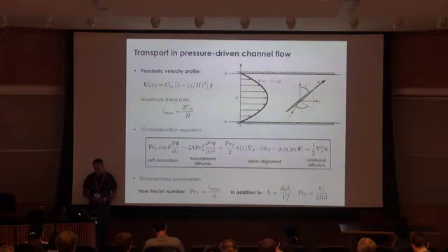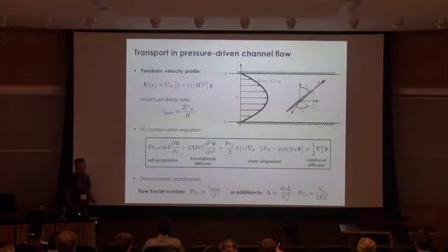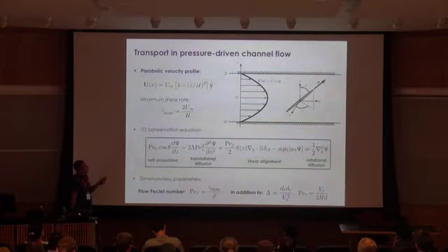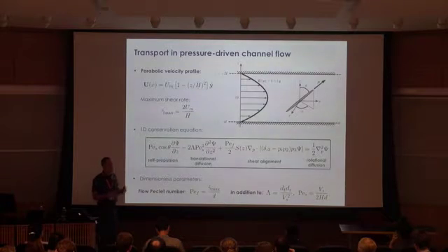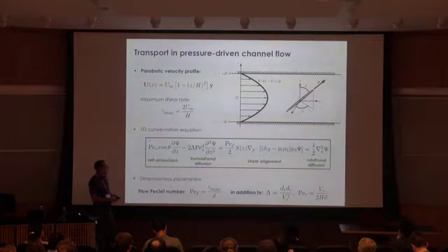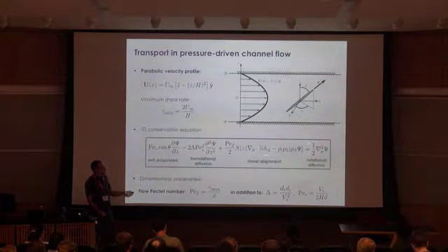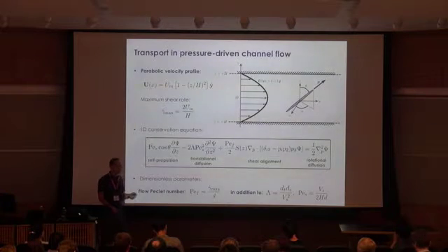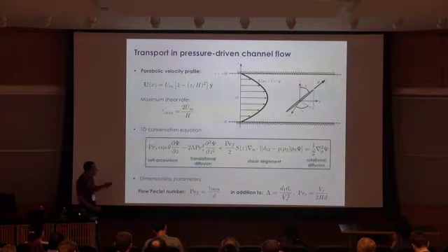Now we can also think about what happens if you add a flow to this, and I'll be brief here as well. So we're thinking about putting a Poiseuille flow here in this same geometry, still in the dilute case. So this is what the equation looks like now. We have one additional term, which corresponds to the shear alignment of the particles under the imposed flow. So this comes from Jeffery's equation. And you can again solve this numerically.